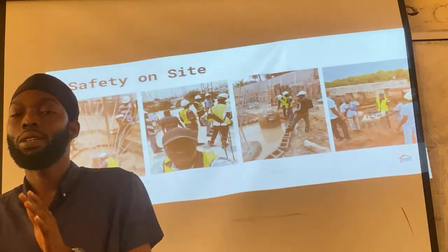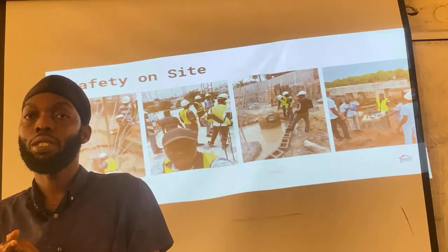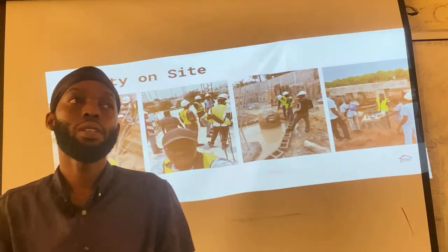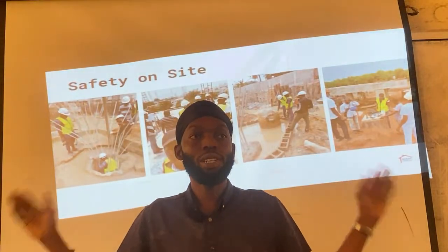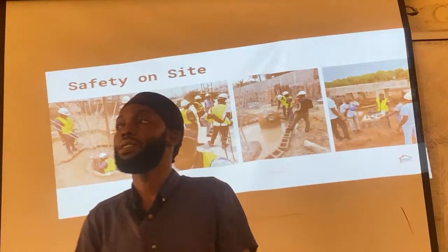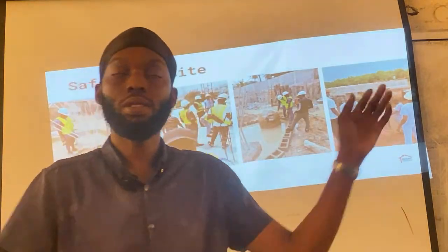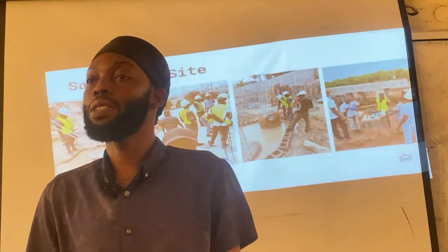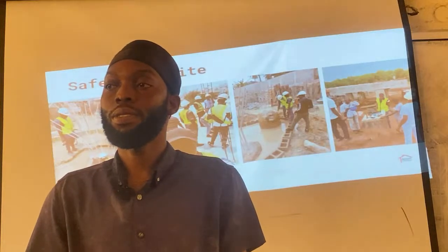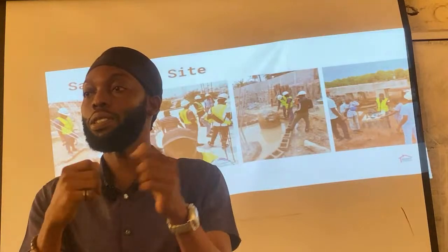Okay, while using the Pundit machine, for example, let's assume this building is not rendered, not plastered, you understand what I'm saying? And we are seeing all the structural elements, the columns, the beams, and want to test them. So for a rough surface structural element, we have our transducers that have very smooth ends.